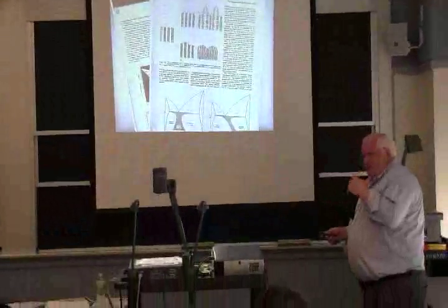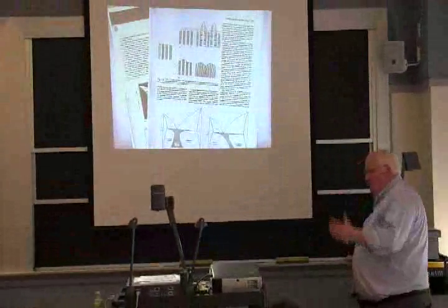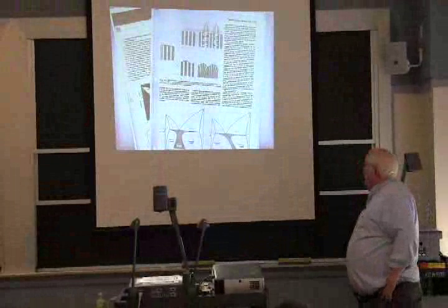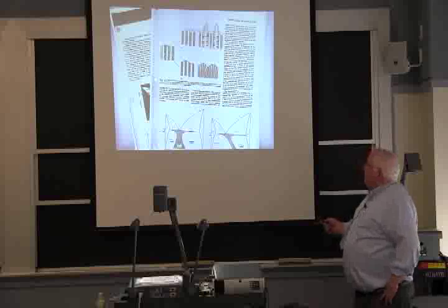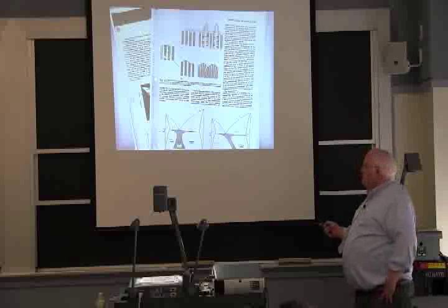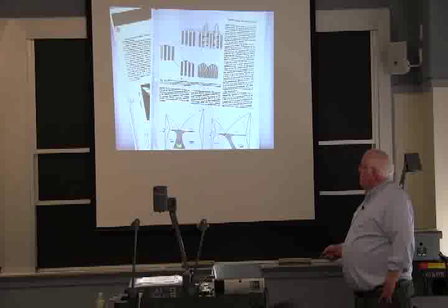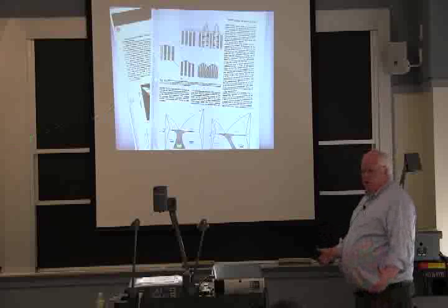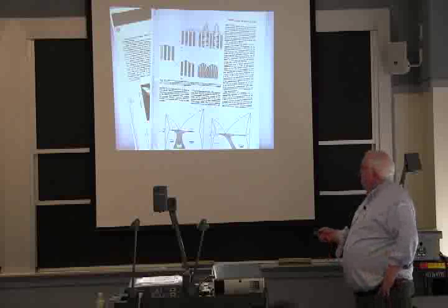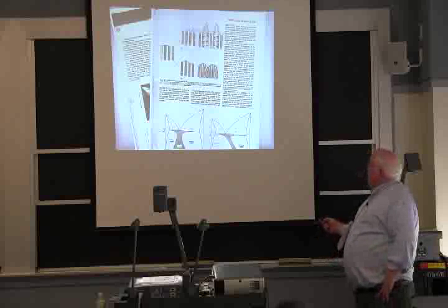They can have very different properties. In fact, that's the definition that J. Willard Gibbs gave to a phase. A phase is uniform throughout in properties, not necessarily in composition, but in properties. So a phase, hopefully, is homogeneous in properties. When you have 2 phases, it's by definition not homogeneous in properties, because each phase has its own set of properties. One of them might melt at a higher temperature.